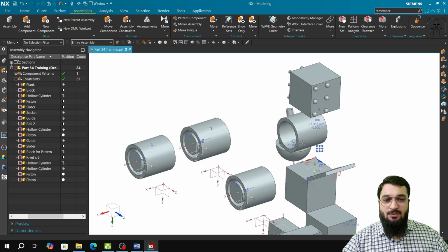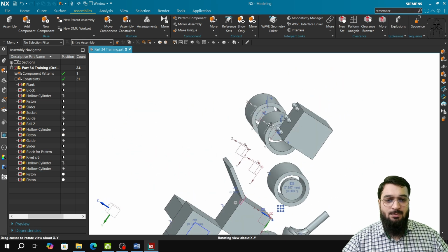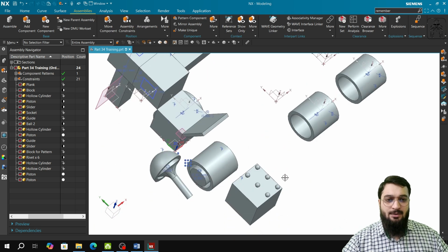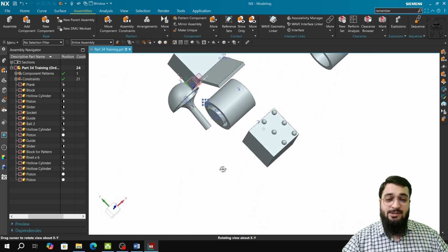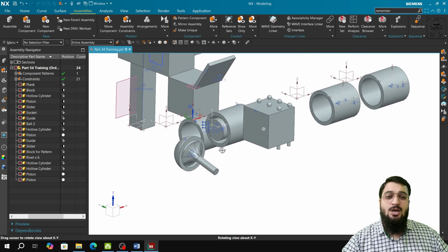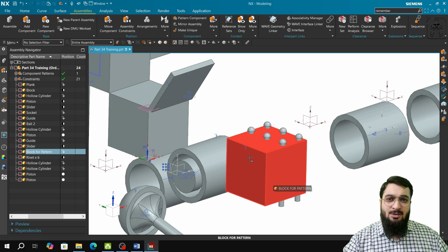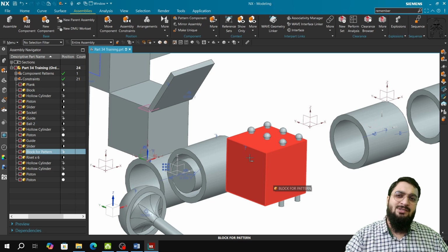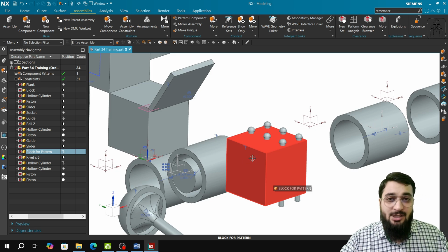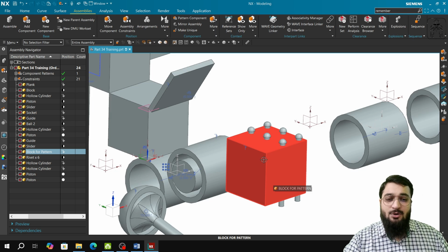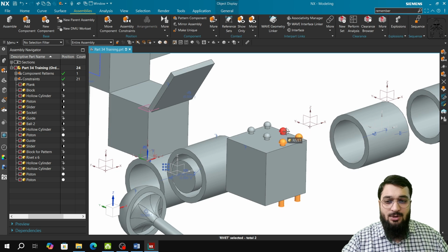So now what we have to do is that I have created a particular part to make you understand the pattern. And also in the previous lecture, the remember assembly constraint lecture, I told you how you can add multiple objects, and by making use of the remember assembly constraints tool, you can just add multiple copies in one single go, like 5, 6, 10, 15, whatever, and you can just redefine the constraint in the next dialog box. So that saves a lot of time for the user, and this particular part has been created by me in order to let you understand how to do that.